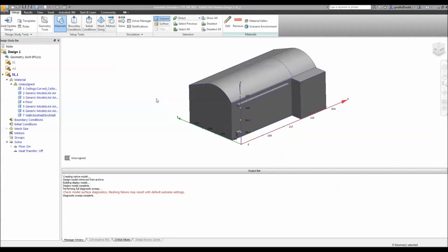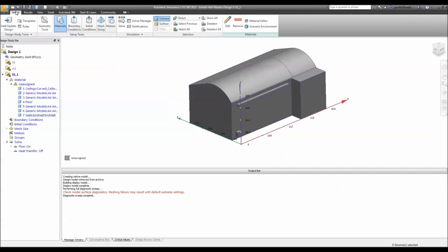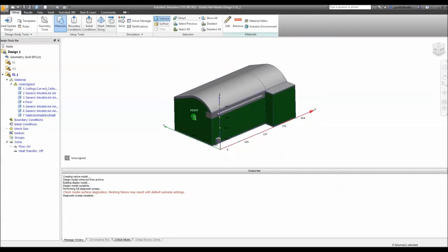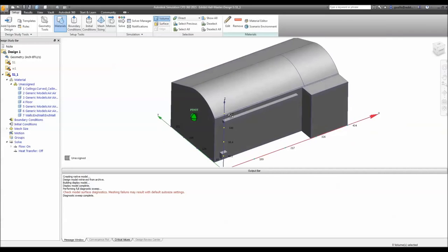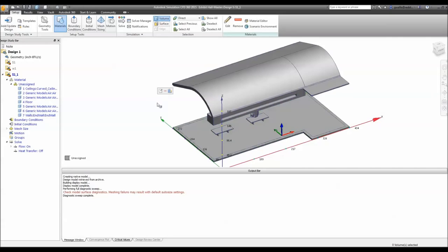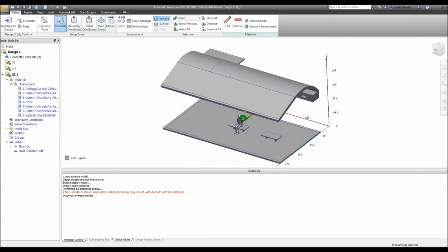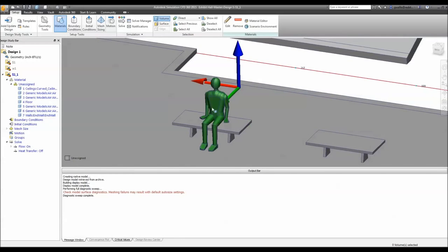Okay, so I just want to introduce you to a few of the navigation tools. First of all, across the top here we have a ribbon. Typically with Autodesk products we have a ribbon, so we can use different types of ribbons. And I've got some tools here where I just simply hold down the middle mouse wheel and pan. I can roll the wheel to zoom, and then I can press down the shift key and I can rotate. Another really nice feature is holding the control key, pressing down the mouse button, and I can hide some of the objects in the room. Very easily just rotate around here. Try and do this smoothly for you because I know you're looking online. And this little guy here, our human occupant, this is what we're going to be interested in today.